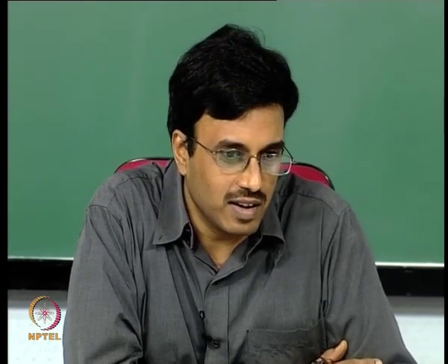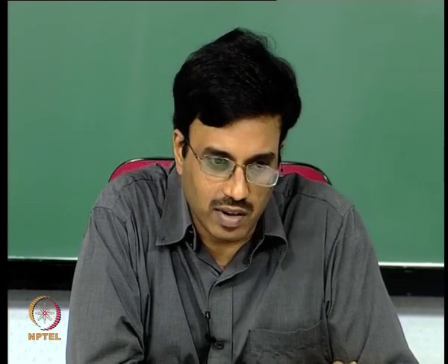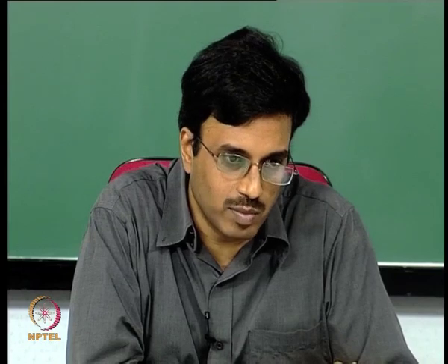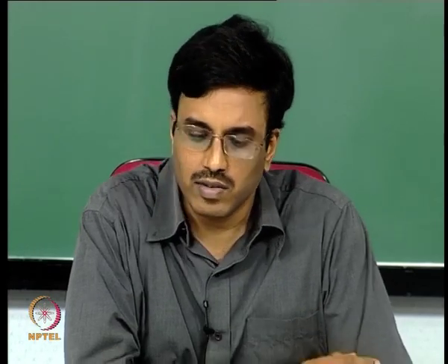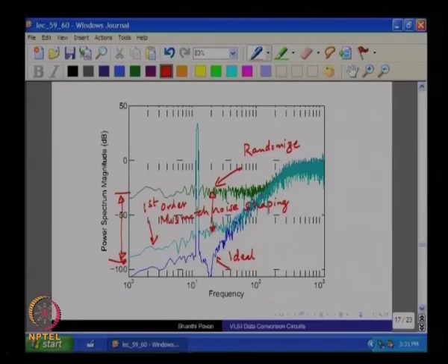So, it turns out that if you do, within quotes, use standard best practices for layout, it is not uncommon to get matching in the order of 0.5% or so, right. Sometimes capacitors, if you do a good job, can even match to like 0.1 to 0.05%, which is the matching at the 10 to 11 bit level. So, even if this is 5% mismatch and you are this much above the quantization noise floor, if the mismatch became 0.5% rather than 5%, what do you think will happen?